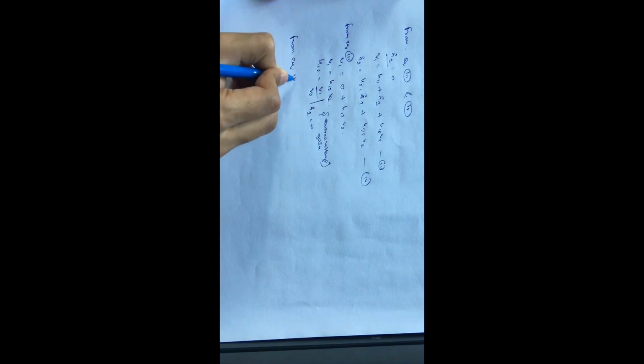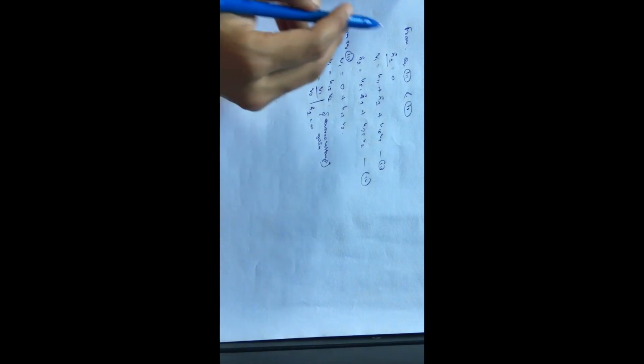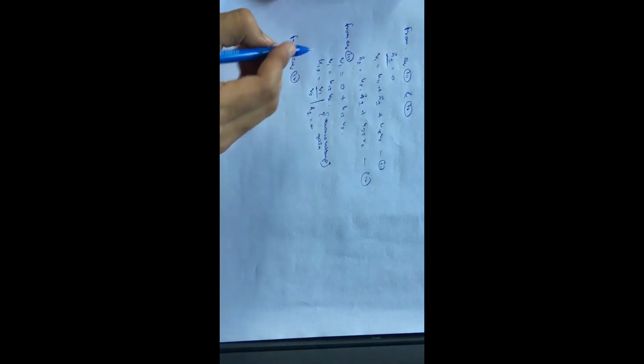And similarly from equation 4, we are considering again I1 to be 0. So from equation 4, I2 equals H22 V2. Now H22 equals I2 by V2 when I1 equals 0, and I2 by V2 is admittance, output admittance.